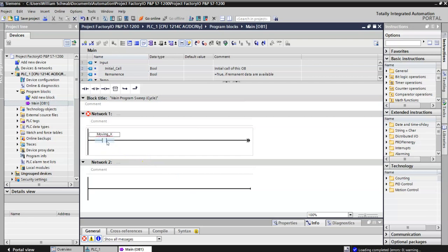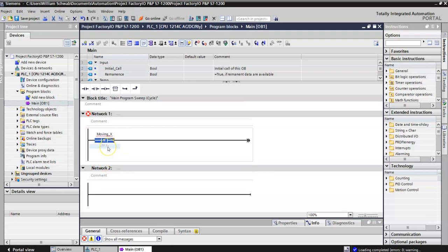So we'll have to change this type of gate. If I click on here, there's this little orange triangle in the corner. If I click on that, I can pull it down. I can have normally open, normally closed. This is a rising edge, P is positive. This is the negative edge. So now I also need, this is a one-shot just like an Allen Bradley. So I'm going to give it a name of ONS1.